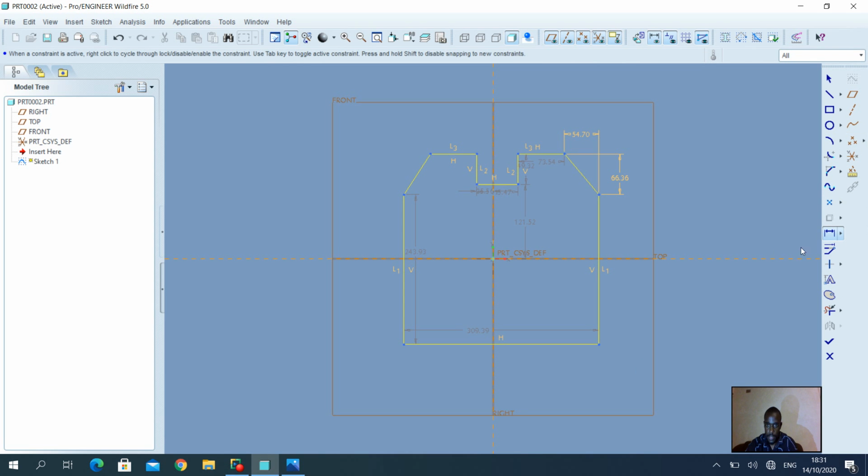So I'm selecting the normal here, and I'm selecting this distance again, and I'll just click right there, because I know this is 30 and this is 15, so it will be just 15 plus 30 divided by 2 to get the distance without really having to subtract a number of things.